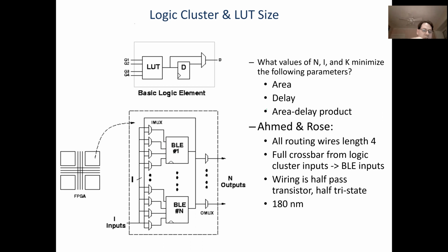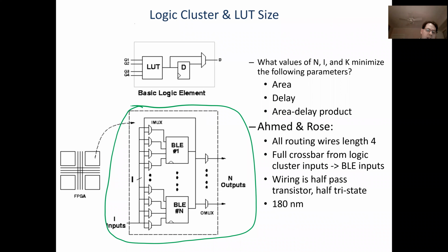And that logic block, shown here, is going to be embedded in an island-style FPGA. So they've got some local interconnect and some LUTs that makes a very small hierarchical FPGA, and then they make an island-style FPGA by replicating those across the chip and putting wiring segments and programmable switches in between them.